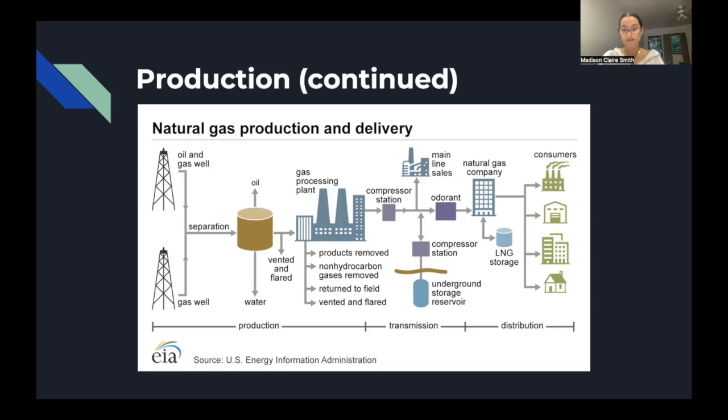Natural gas processing is complex and involves a series of stages to remove oil, water, HGLs, and other impurities such as sulfur, helium, nitrogen, hydrogen sulfide, and carbon dioxide. The composition of the wellhead natural gas determines the number of stages and processes required to produce pipeline quality dry natural gas.